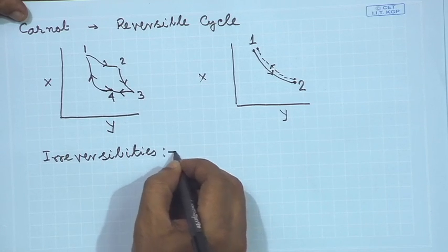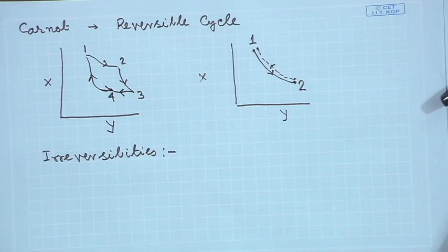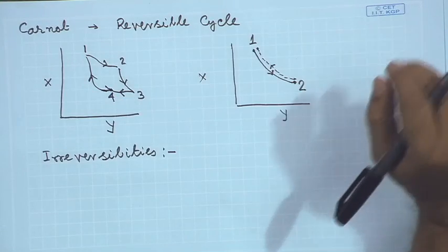During a process there are many irreversibilities, because there are many dissipative actions. Like when there is a motion and one solid moves over another solid, there will be friction. This friction is a dissipative effect, due to which some amount of energy will be spent and that cannot be recovered back in useful form. That will go to some other form which cannot be reused again with simple means. So, this is some sort of irreversible process.